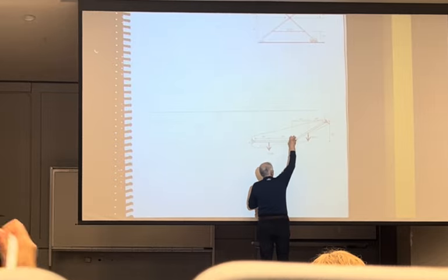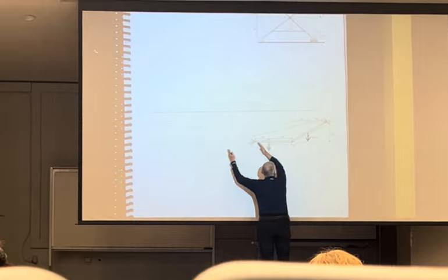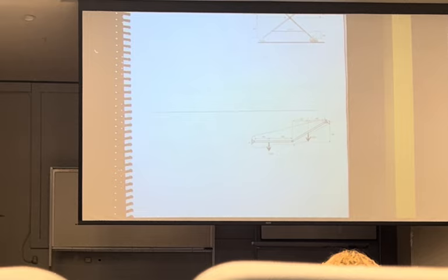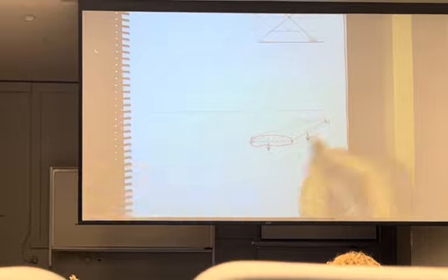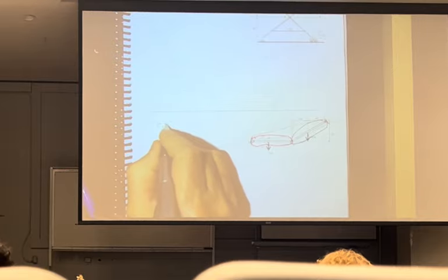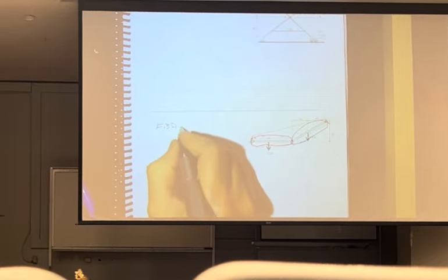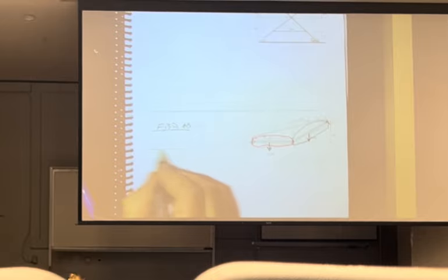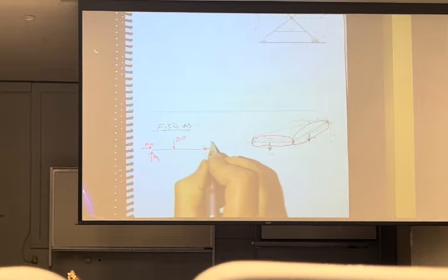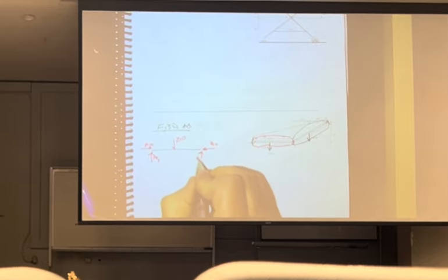So what I'm going to do is take this pin out and separate it into 2 pieces. So I'm going to draw a free body diagram that looks like this. 2 free body diagrams, one this way, one that way. So the first free body diagram of AB will look like this. I've got an AY, an AX, I got 210 external load, I got a BX, and a BY.